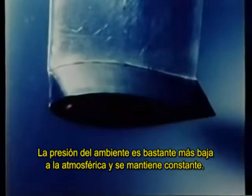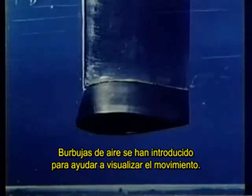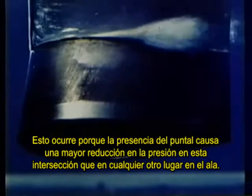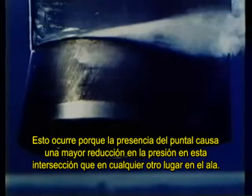The ambient pressure is well below atmospheric and held constant. The flow speed is being increased at a uniform rate. Air bubbles have been introduced to help visualize the motion. Cavitation occurs first at the intersection of the hydrofoil and the strut. This happens because the presence of the strut causes a greater pressure reduction at this intersection than elsewhere on the foil. But we will confine our attention to the foil section away from the influence of the strut.